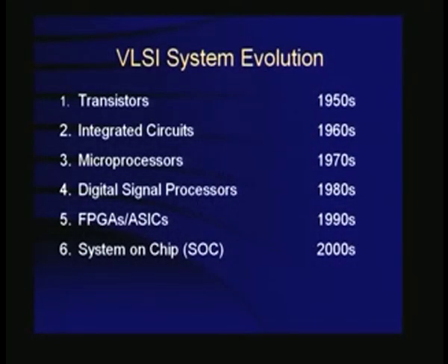And then finally, the concept is now evolving more and more towards system on a chip. That means the entire system, like a computer, which has a memory, I/O, peripherals like serial I/O, DMA, or it can even be systems such as a digital camera, a complete MPEG decoder, this MP3 player. They talk so much about all these different devices today, all of them in a single chip. For example, a digital camera looks so small and tiny, yet one chip has everything in it. This is called system on a chip. It is also called embedded systems. People say embedded systems today, and these are nothing but systems on a chip, a single chip on which the whole system is integrated.